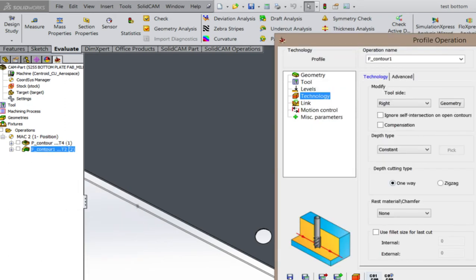So, one easy way that you pretty much can tell if you're climbing or not is if your tool side is left. That almost always works. So if your tool side has to be right, you're probably not climbing. Okay? Questions there? Profiling. That's profiling.